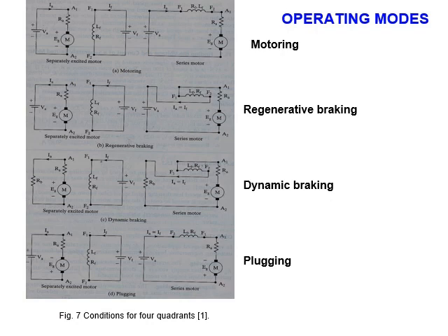or the current. What types of modes will we have for the motor? The motor will work in 4 different modes, in terms of voltage and current, or in terms of torque and speed. Sometimes both torque and speed are positive. Sometimes only one of them is positive, either the torque or the speed. Sometimes both are negative. These are the 4 modes.